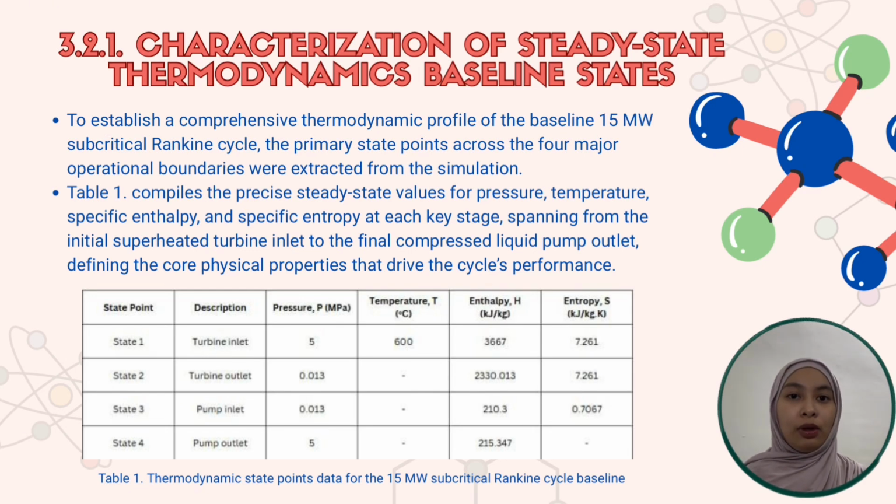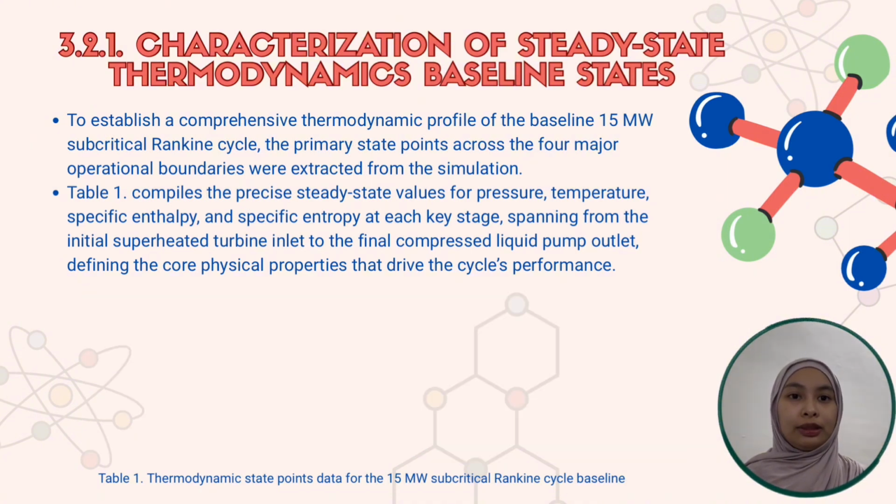As you can see in table 1, we have compiled the precise steady state values for pressure, temperature, specific enthalpy, and specific entropy at each key stage. This tracking spans from state 1 at the initial superheated turbine inlet, operating at 5 megapascals and 600 degrees Celsius, all the way down to state 4 at the compressed liquid pump outlet. These values define the core physical properties that drive our baseline cycle's overall performance.